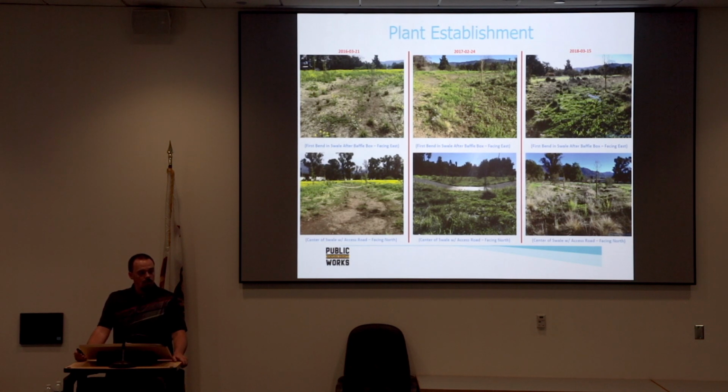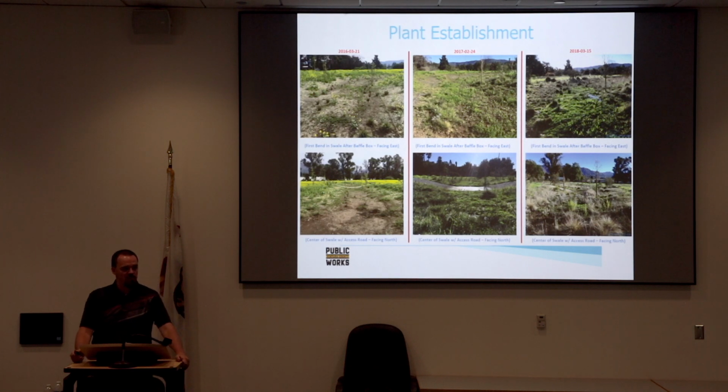This can be used in swales that are prescribed in the TGM? They can. It's just an easy replacement for turf grasses. If we can't put turf into a swale, you can put in drought-tolerant natives that have similar pollutant uptake. Correct. Fescue grass. There's also other grasses you can use. Again, I don't know all the common names in that. I'd like to become an arborist at some point, but I'm definitely not there. But there's fescue grasses, other types of bunch grasses you can use. Generally, those are good to space out, maybe 2 feet on center, staggered, so that when those other larger plants and bushes are taking 3 years to develop, the bunch grasses are still impeding the water, slowing it down, kind of acting as a dissipation device.